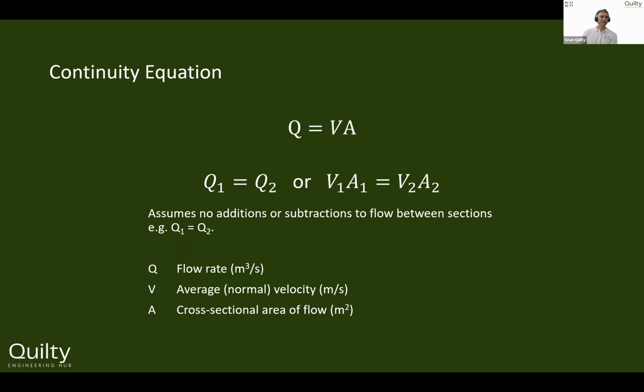The continuity equation, especially in channel design, we're assuming that it's steady flow. The flow is not changing throughout our typical section. So that means your flow at one point is equal to your flow at your second point. And that's where the continuity equation comes from.